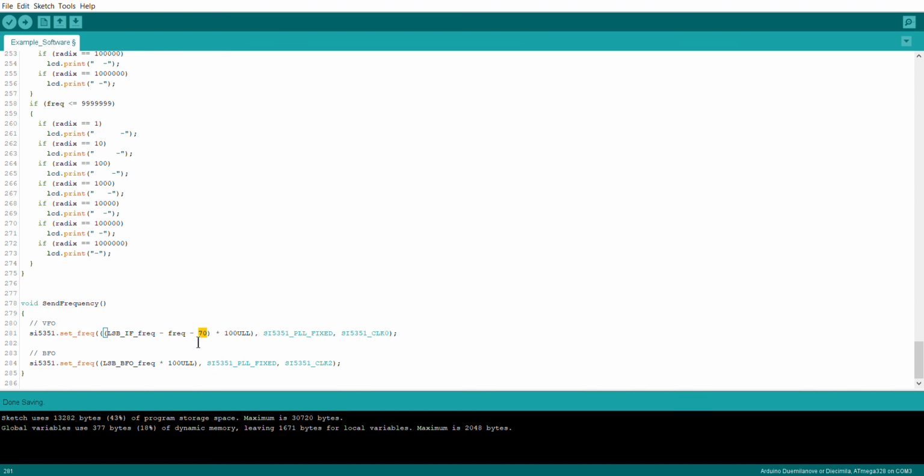So once you've done that, you then say that's where the variable frequency needs to be in order to mix with the incoming RF and place the IF and the intelligence just on the high side of the crystal filter, so therefore our desired lower sideband is sitting inside the passband of the filter. So that's basically all done there. Now if you're doing down conversion or any other type of scheme, then this is the part of the program where you would make those changes.